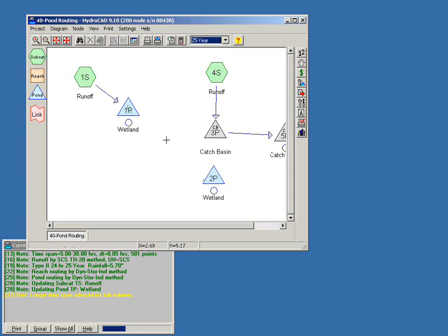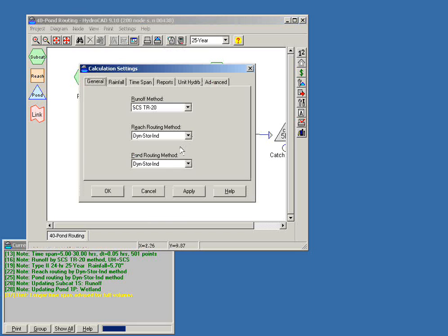We can also do the same thing by doing a control drag on that node, and that brings in an exact clone of the node. We can now take the upper flow and route it to the lower one. So now I have two absolutely identical ponds. They're at the same elevation. So the lower one presumably is going to fill up and create some kind of tailwater issues on the pond downstream. Let me just make sure I have a setting right here.